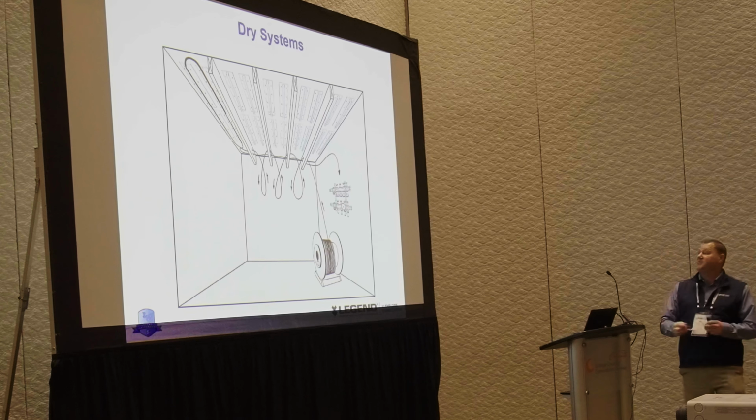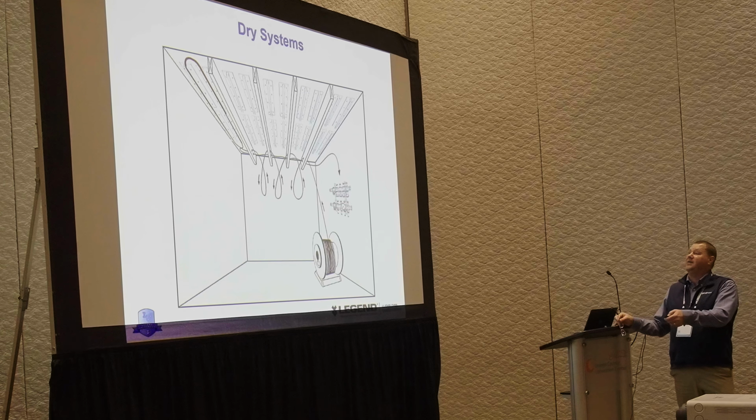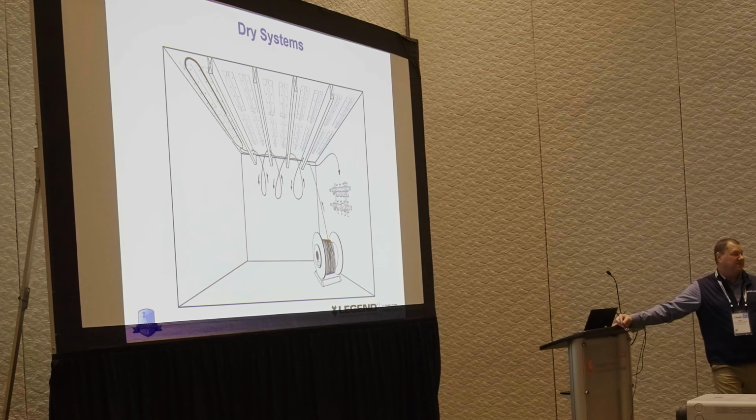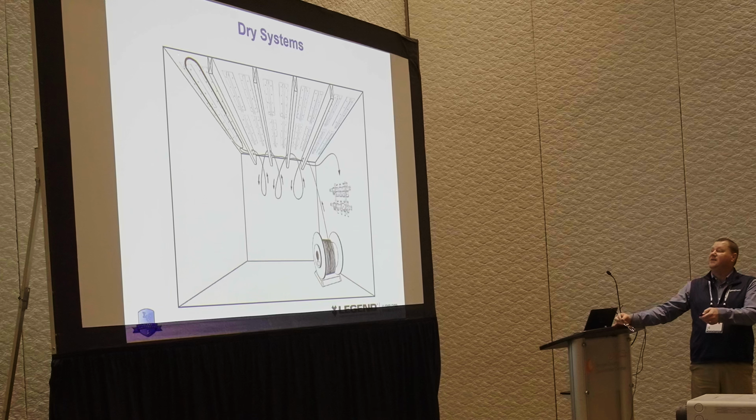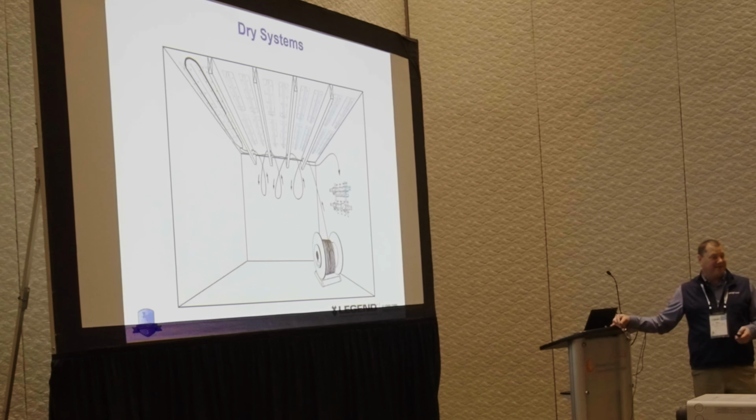In this situation, it can flop around. If you've got areas for it to expand here and back in here, it will, and it can eliminate some of that ticking sound that you will get in those heat transfer plates. If you pin down here with a staple and pin everything down here, it may look cool when you install it, but when that tubing heats up and it starts to expand and contract, it's all pinned down and won't go. Yeah. It'll break the staple. It'll break the staple. It will.